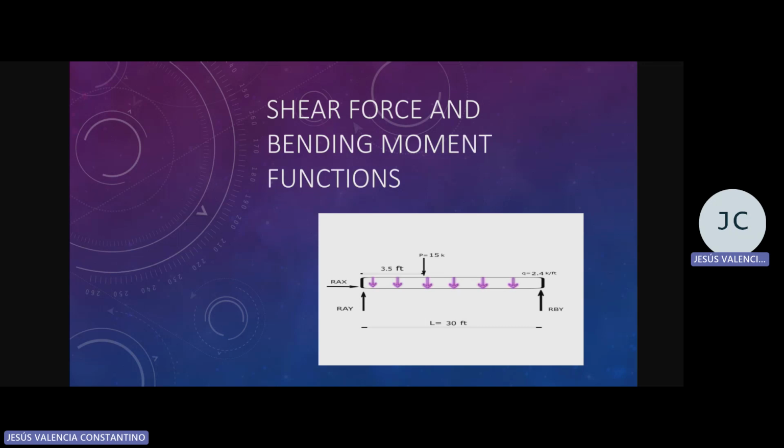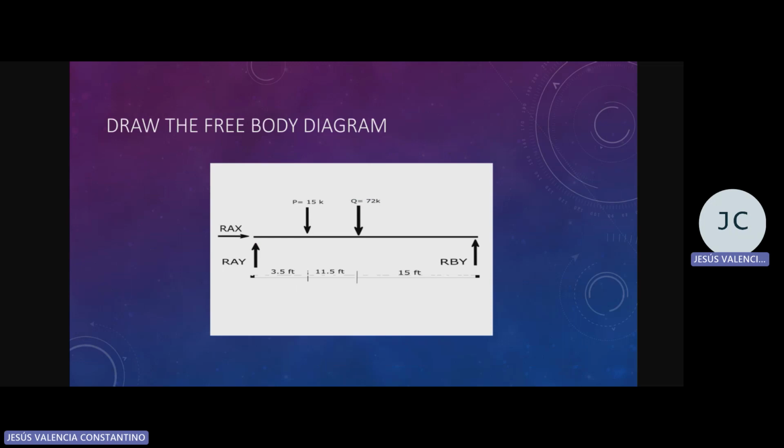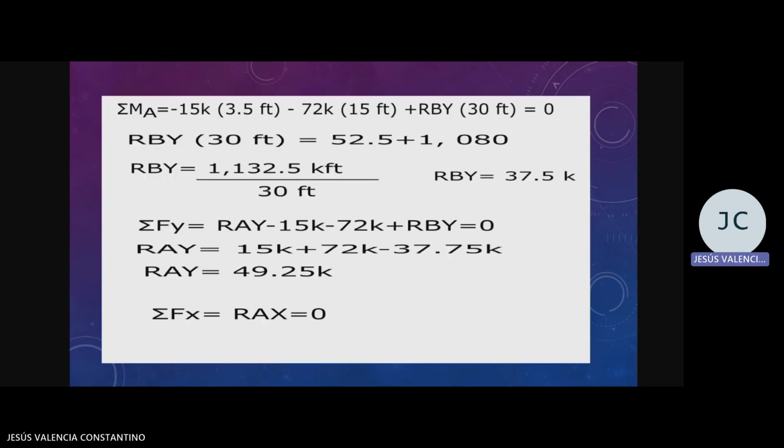The centroid of the distributed load is located by multiplying the base by height as it forms a rectangle. Similarly, the centroid for each rectangle is located at the midpoint. Next, we proceed with the summation of moments at A, as it is a fixed support and has both X and Y components.